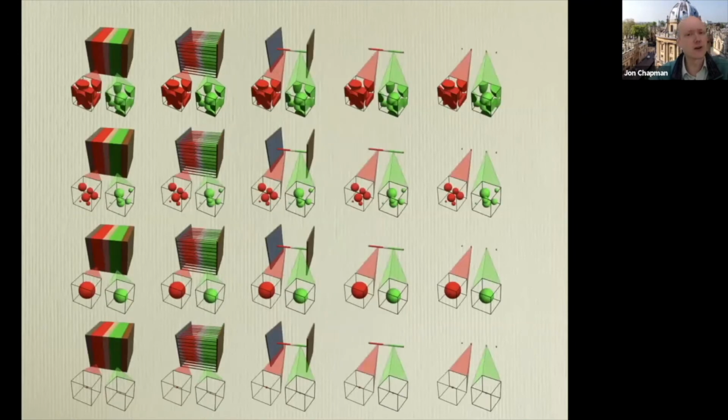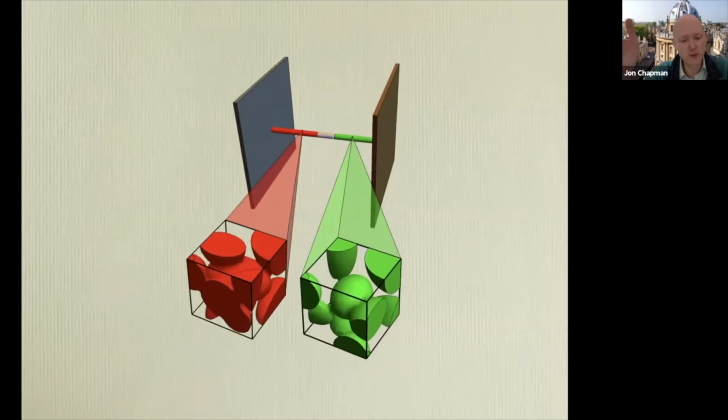If the current collectors were even more conductive than that, then the potential would be uniform on the current collector, and all these one-dimensional models would be the same. So instead of having to solve a lot of them, I only have to solve one of them. I still have a two-dimensional problem to solve at the ends, because depending on where I place my tabs, the current distribution in the current collector is non-uniform, and I get a resistance from the current collector. I can work out what it is by solving a single decoupled two-dimensional problem. That's quite a nice problem to solve, because it allows you to play with the geometry of the tabs in order to optimize the current collector in terms of its resistance and maybe its thermal properties.